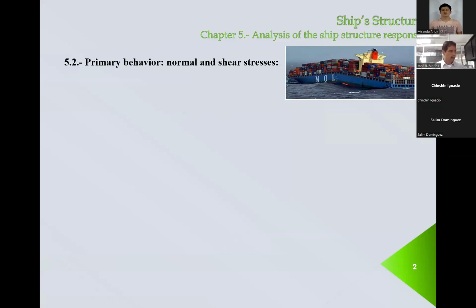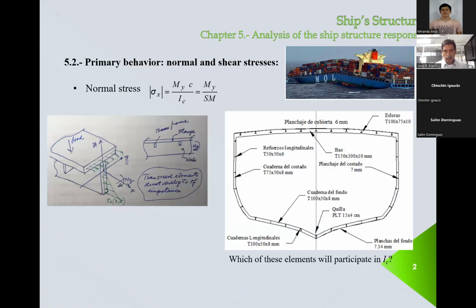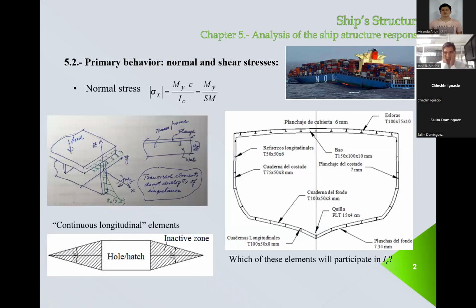Okay, so all of these people, this is important for me. Why? Because this means that when you calculated the inertia, or when you deduced the formula for the inertia in this problem, what we did was we considered normal stresses, right? And you integrated these normal stresses multiplied by the differential area, and multiplied by the vertical position. And you make that equal to the bending moment.